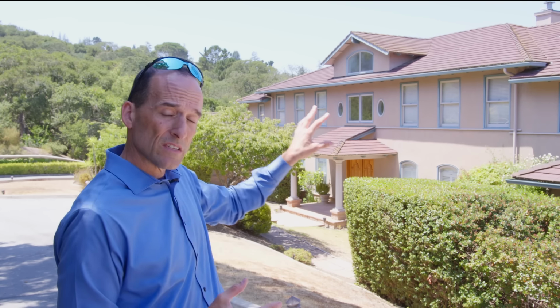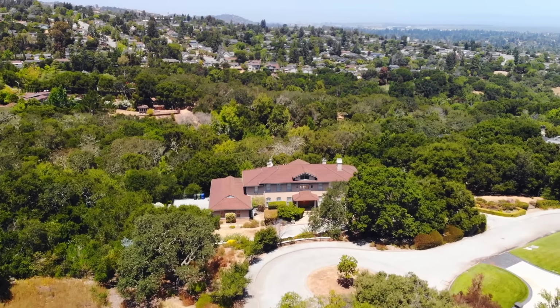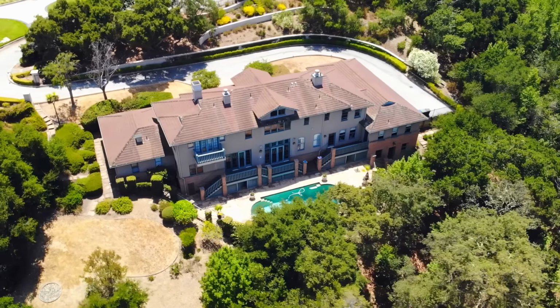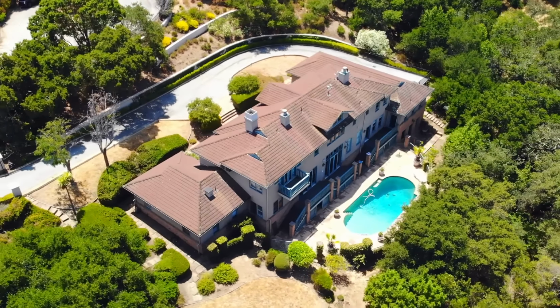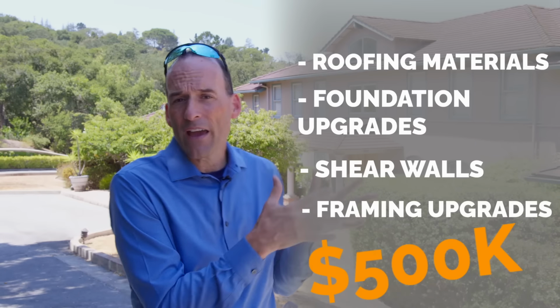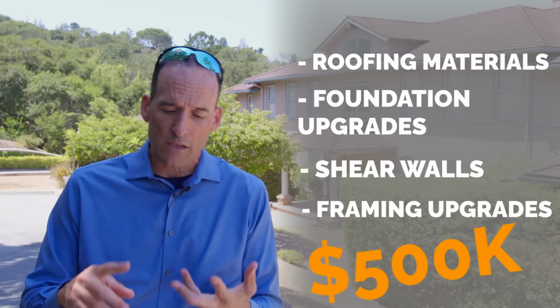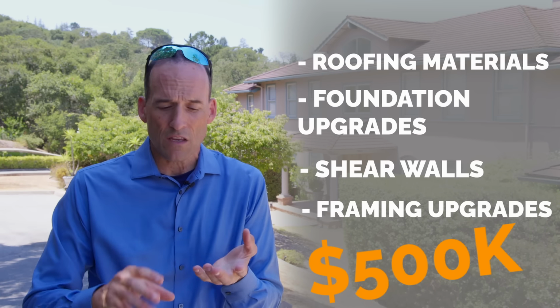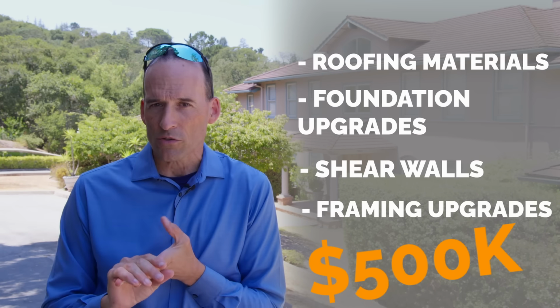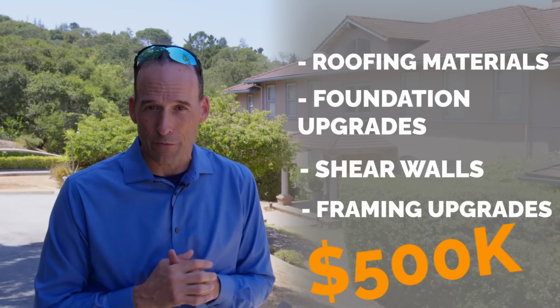And we found that if we used a lightweight roofing material and took away this tile, we could actually use the existing house's structural framework and not have to do a seismic upgrade, even though we are adding insulation on the walls and the roof of the house. We are actually saving about $500,000 between roofing material, between foundation upgrades, between shear walls and framing upgrades, about $500,000 reduction in the cost of this project just by reducing the weight of the roofing material.